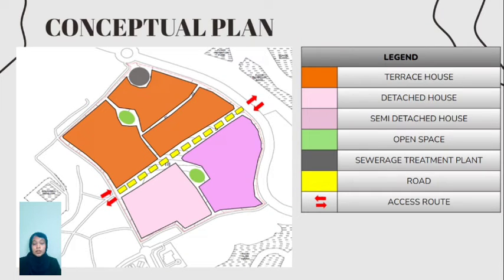The placement of sewage treatment plant in this concept plan has been assessed through study in topography, namely slope, elevation, and cross-section. According to the study, the lowest contour line is on the right side at 9. It should be at the lowest level of the site. Also, it should be located near to the stream or river for discharging the treated wastewater. Accessibility for maintenance work. However, for sewage serving relatively undeveloped areas adjacent to metropolitan areas, it is advisable to construct initial facilities for a limited period. Nevertheless, right-of-way for future larger trunk sewers can be acquired or reserved.